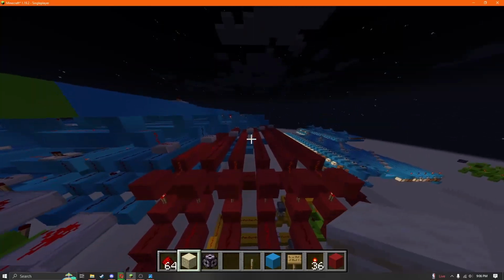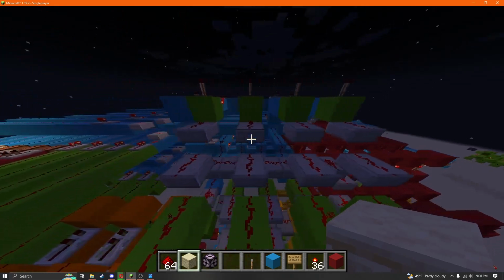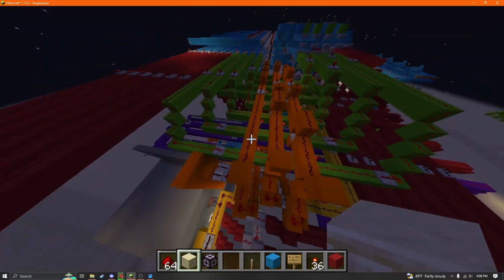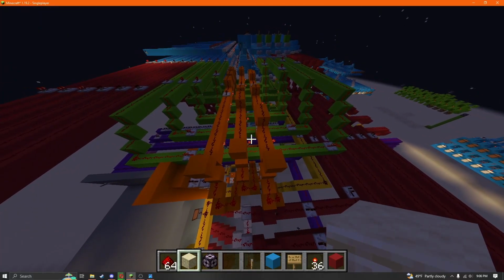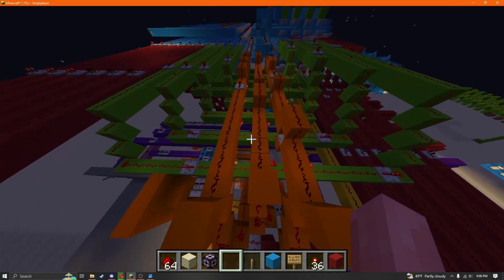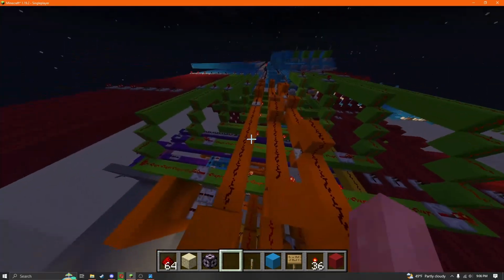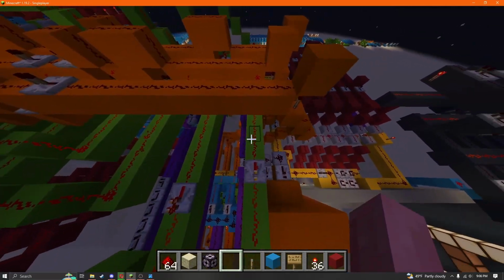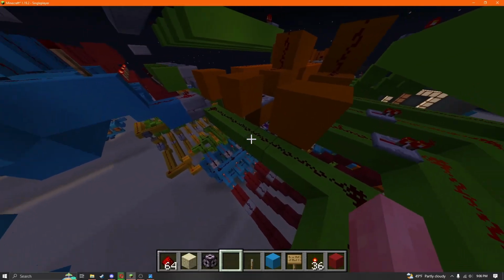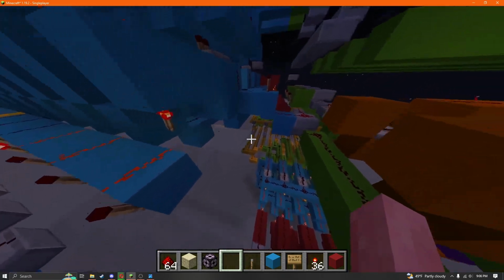So we got our data coming up and sent down there, and we need to pick which register we're going to save the data to. So in this case, we're picking the 0th one, and you can actually see this orange control circuit controls which register we're writing to at the time, which register is selected by the program counter. So right now we have the 0th one selected because all 3 of these bits are 0. The redstone's not on. We can see this represented down here on the green by all of these being on except for this one, which means that this is the 0th register.